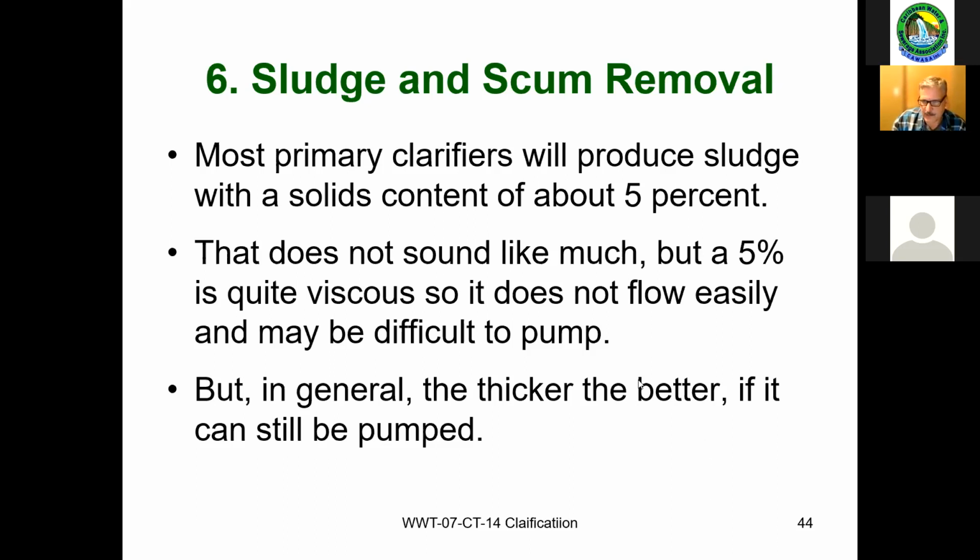Earlier, a gentleman mentioned that the sludge from the primary clarifiers is taken directly for land disposal or drying. Do you happen to know what percentage that sludge is at? No. So if it's really watery, it might be anywhere around 3% or so. A little thicker would be about 5%.